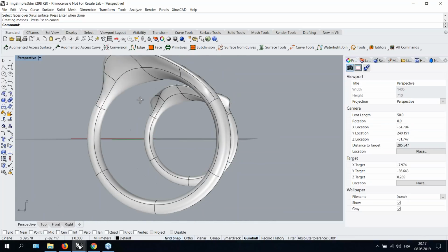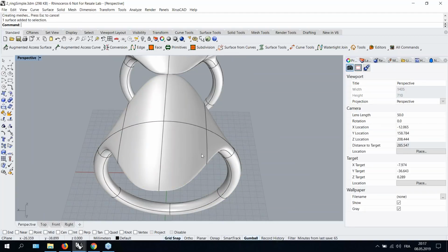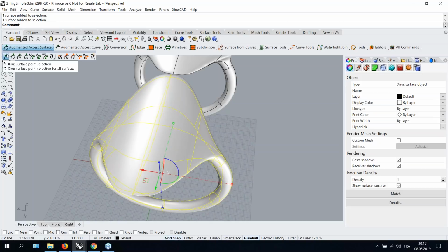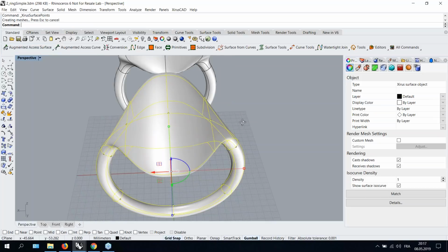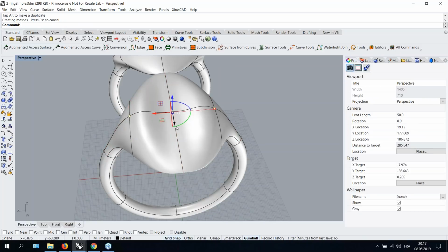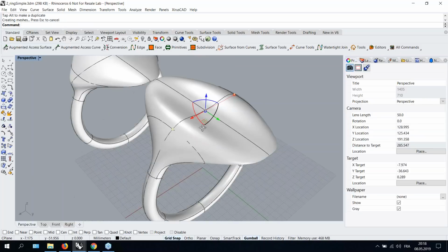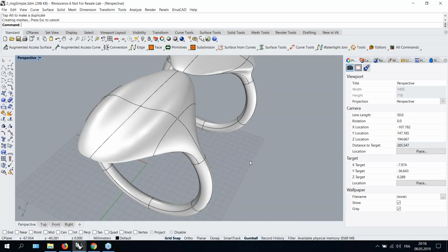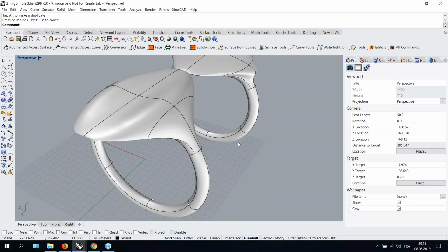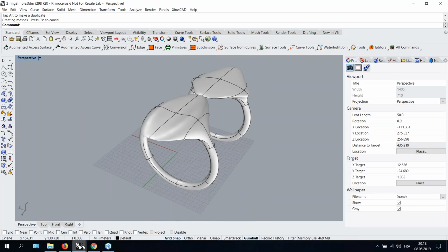and you see that we got these new parameter lines inserted, and actually all the new edges or vertices that you see have the same properties like any other control point, which means now, for example, I can go again and display the control points. I can move them a little bit around, and you see, so this is all still very, very smooth. You can subdivide again if you want to insert more local control or add more details if you want. So these are some of the standard operations.